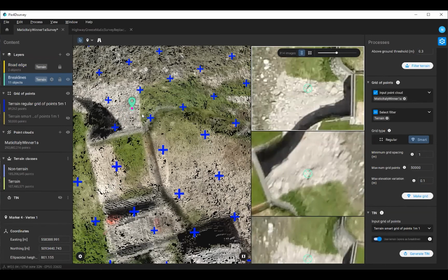riverway. And in this case, if you have a known coordinate for this, you know that they actually recorded it at not 388.991, but it was just 0.98. So you can really manually adjust these so that you can nail that exact elevation that you need it to be. And so as you make these edits, these are tiny ones, it's actually moving in 3D. So you can always get the exact location you need, either for a marker or for an individual vertex. It's always going to be applied perfectly, however you want that to go in.